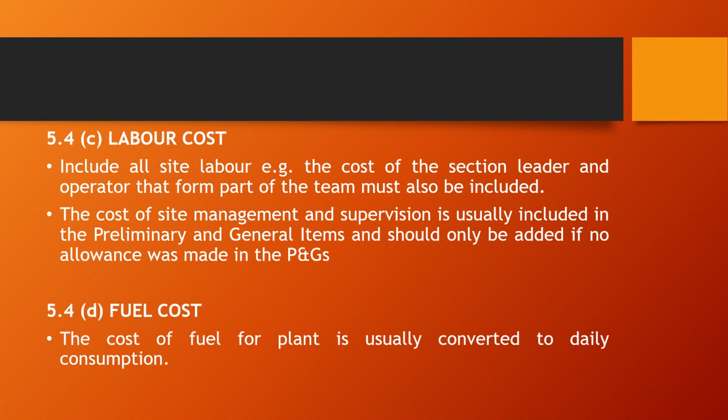Your fuel cost for your plant, you would also include as a function of daily consumption. For example, typically a TLB would use about, say, 15 liters an hour. So if you know that your TLB to hire at a dry rate is, say, 350 rand an hour, then you would add on a consumption of 15 liters of fuel an hour. You would add the cost of that fuel per hour onto the hourly rate.